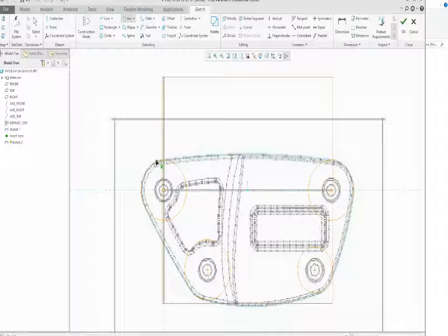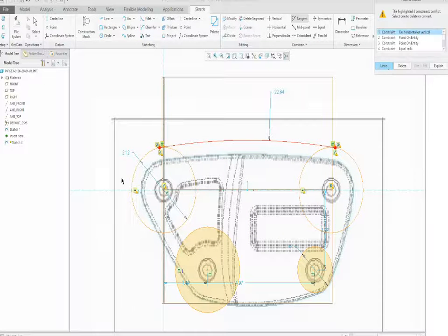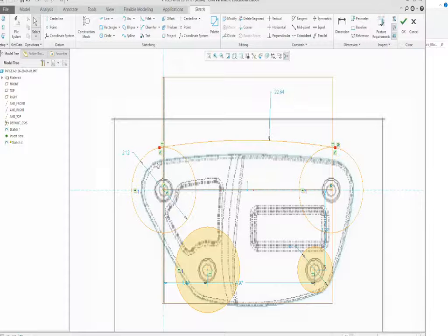The arc will attach over here. Don't accidentally pop over here. And it'll attach roughly to the attachment there. So make it roughly about the right size, and then we need to hit tangency on it. So we'll hit tangency, tangency, and then tangency, tangency. You can hit undo on that if it's got a horizontal coming across there. Then you need to right button click until it turns blue, touch it with the left button, and then hit delete on your keyboard. Now you can get the tangency.